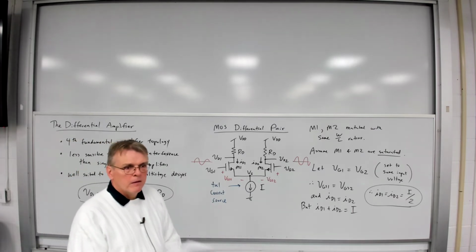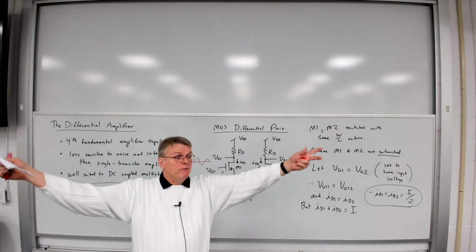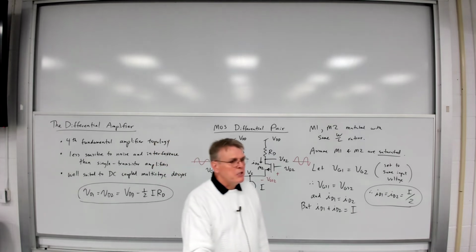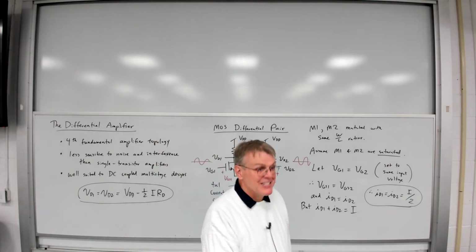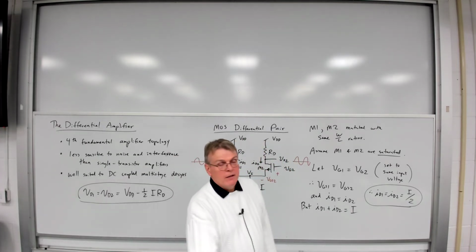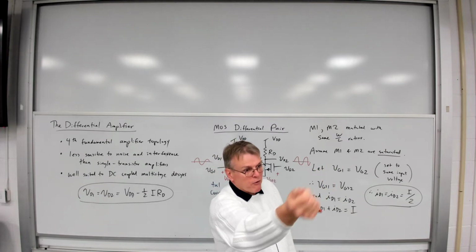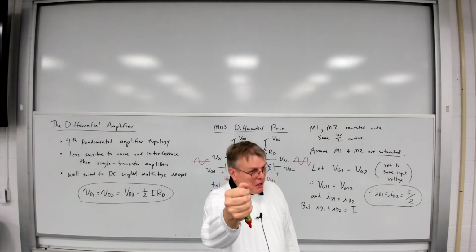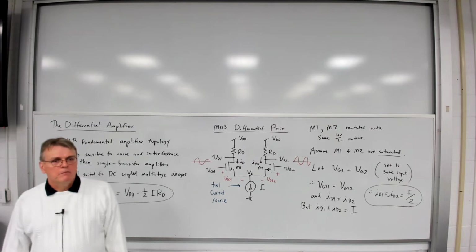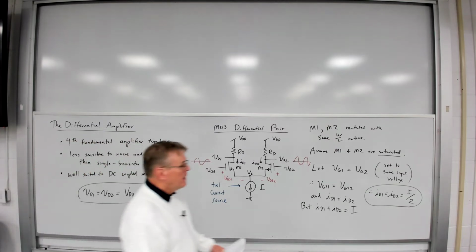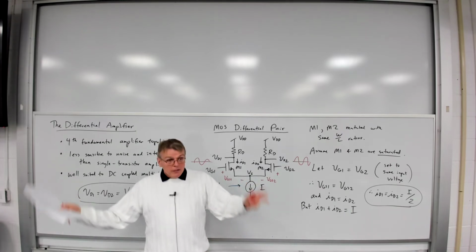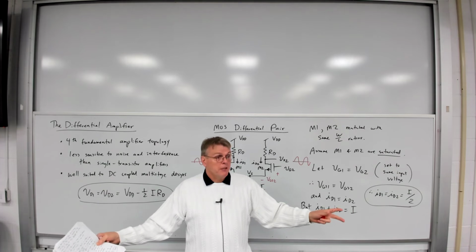What is the source of the 60 hertz? Oh, it's going to be the electromagnetic field from your power lines. In other words, think about it. That 60 hertz coming out of the wall is not just electricity, it's electromagnetism, okay? You can easily pick that up. If you ever take an electric amplifier, unplug it, and wave around a fluorescent light, you'll hear that hum. That's a real interference problem you'll have, for example, for high-end audio. So that's everywhere. There are plenty of other noise sources, but this is the one we're all very commonly used to, because we literally are living in a 60 hertz electromagnetic field, all of us.